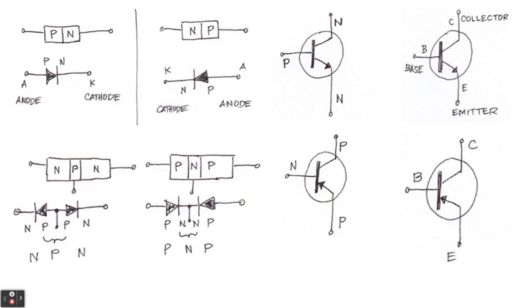On the other hand, if we put together P-type and N-type and another diode, but back-to-back now, this time is the cathode, N-type, P-type, then it's like we have P and P. So these two are the diode equivalents of the NPN transistor, and this is the diode equivalent of a PNP transistor. Now on this side, we have here the symbol for our BJT.